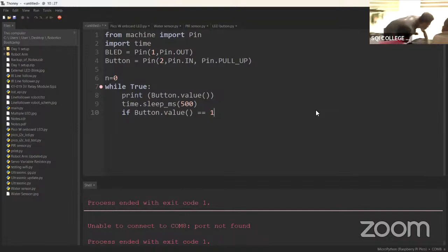It's not working. Okay, introduce a delay first. The thing is, if you don't introduce a delay, this serial monitor cannot pick responses that fast. If you don't put a delay, it will just print what it has printed since time passed. Before this, all these ones have been printed before you know it. As soon as you run the code, it has printed like 1 million of it. So if you don't introduce a delay, it will just keep printing what it has already printed in time passed. If you introduce that delay, you have more data responses.